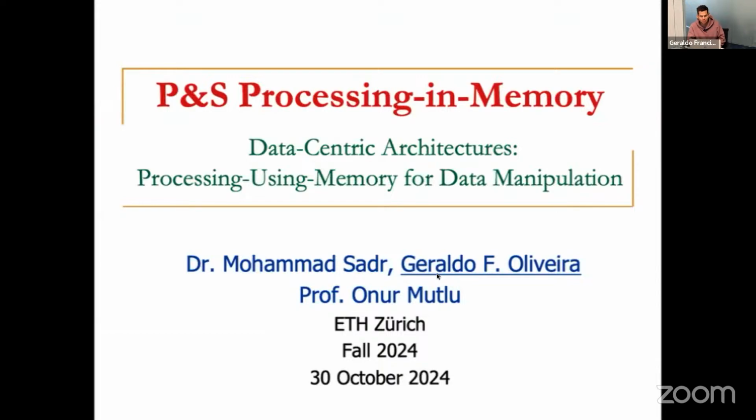So we started really simple today, showing how we can do in-DRAM data manipulation using the operating principles of how the DRAM itself operates, using back-to-back activations in RowClone, and how we can improve the communication path inside the DRAM subarray or a DRAM bank, so we can further improve the throughput of those in-DRAM row copy operations. So we are going to start really easy, with simple operations.